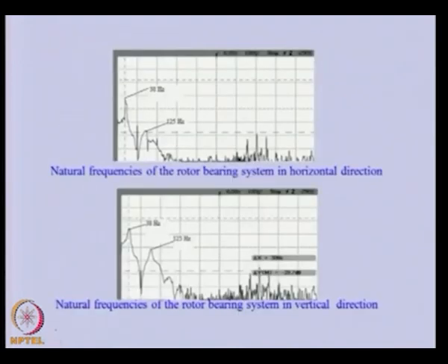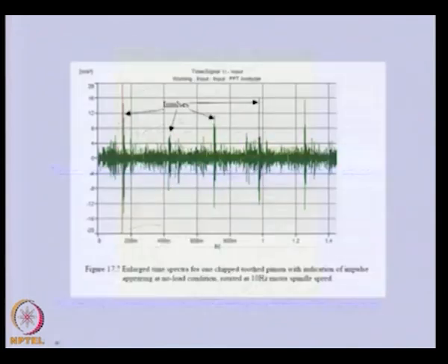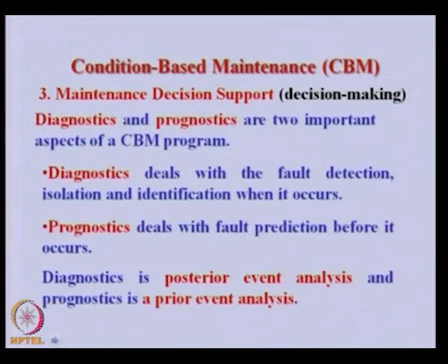So some data are frequency domain data. Free vibration analysis we can perform, and we can pinpoint the natural frequency of the system. So the predominant peak we can collect, and that will be our database. Or, as we have seen in the previous lecture for gear, if we have a chipped tooth of a gear, then we can have this kind of impulses. So those informations can be collected. These are some of the data types, but we can have more of such types.